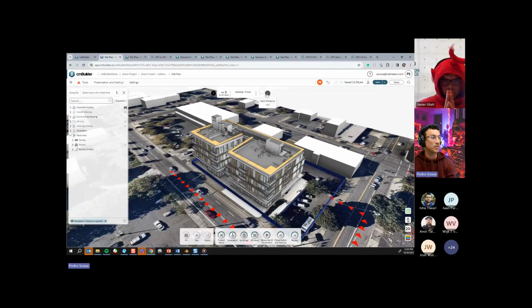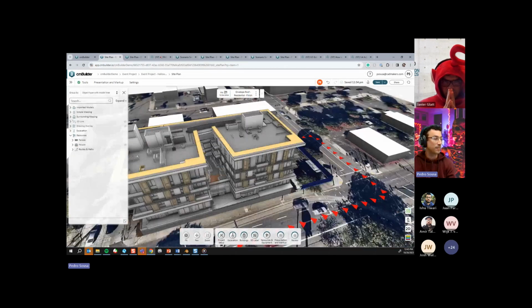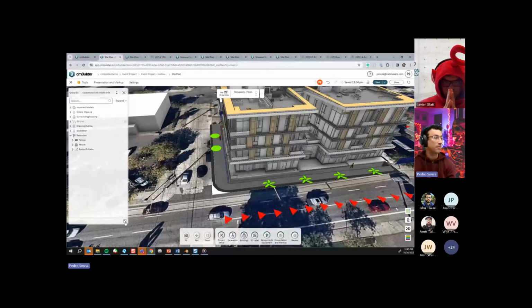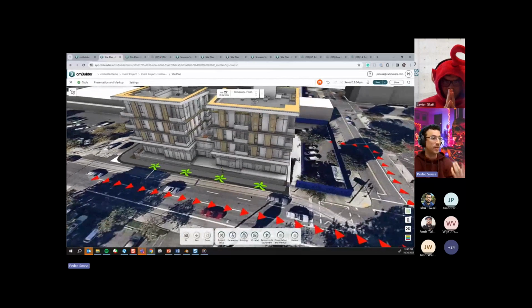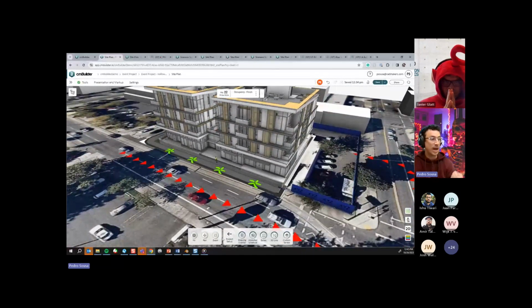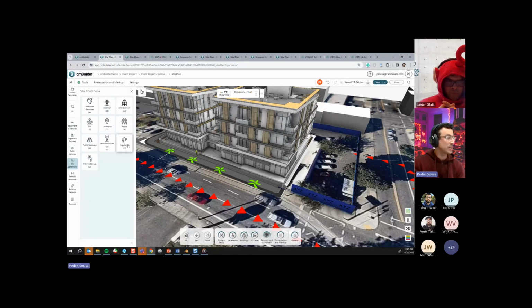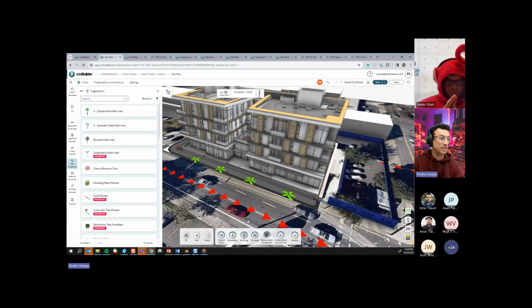So for example, if I go into my last milestone over here, I have now this drawing that we created just to show that landscaping. From this point onwards, you can add the trees if you want, and so on and so forth. Just to reiterate that we do have a lot of vegetation available in our resources library, right? If you go into site conditions and click on vegetation, there are a lot of trees over here that you can use, and I could simply drag and drop these to create the 3D shapes for them.